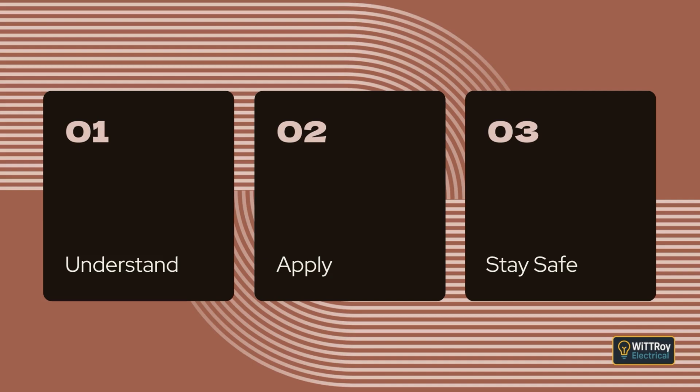Clause 3.9.8 Prevention of mutual detrimental effects between services. Wiring systems must be arranged so they do not adversely affect other electrical services or non-electrical services. Clause 3.9.8.1 General. This includes preventing detrimental effects between different electrical installations, different parts of the same installation, circuits of different voltages, safety services, non-electrical services such as gas and water supply, and telecommunications or data cabling.